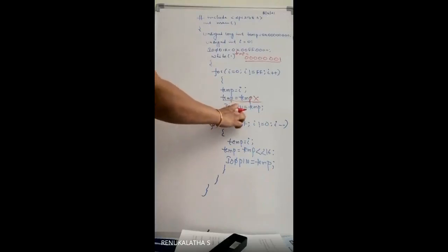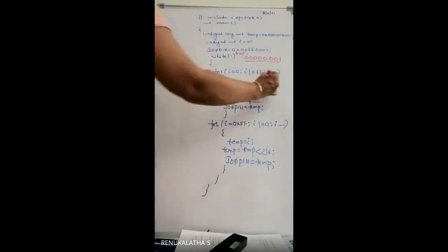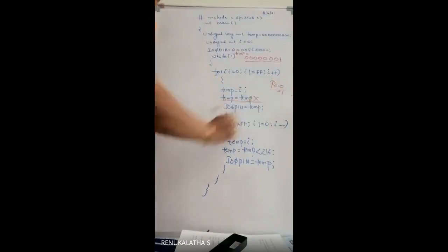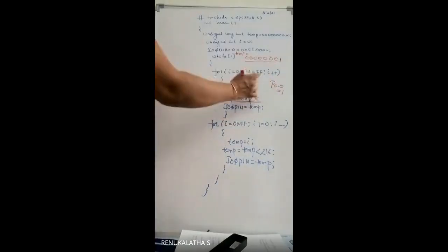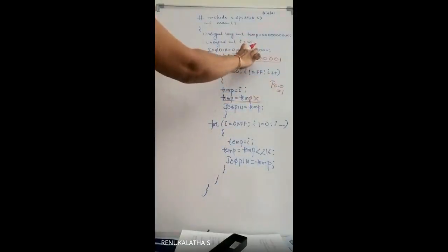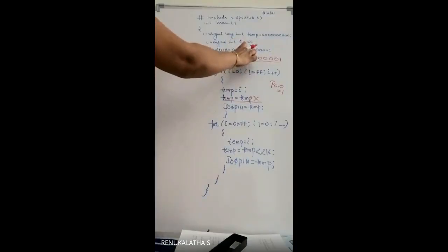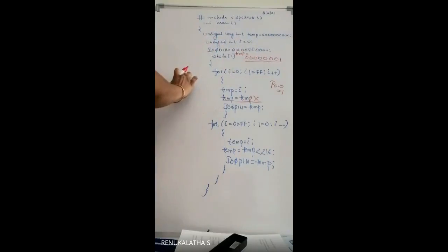The same thing will be placed onto port 0, so P0.0 will be equal to 1, correct? Yes, ma'am. But according to our declaration of the IO0 DIR register, through which pins of port 0 are we sending the data? We are sending the data from P0.16 to 23, those 8 pins.